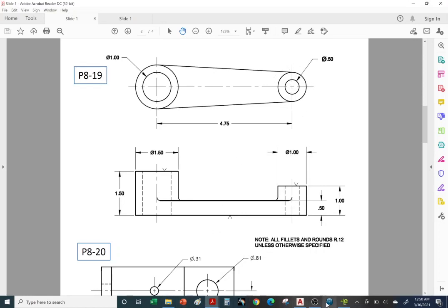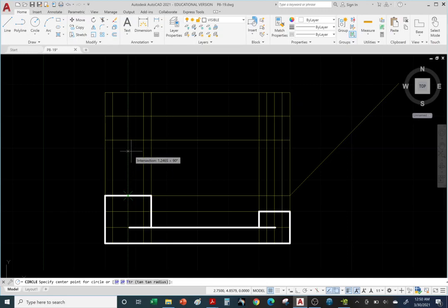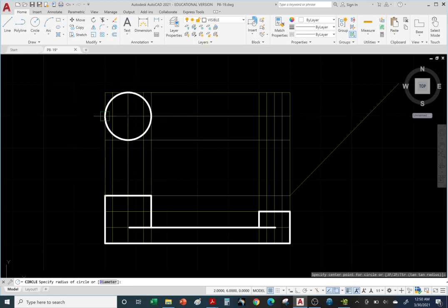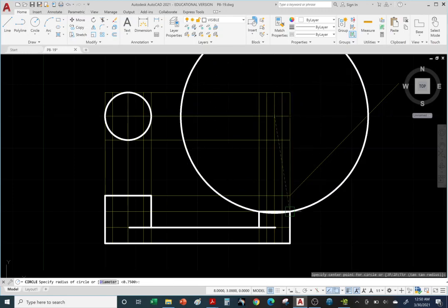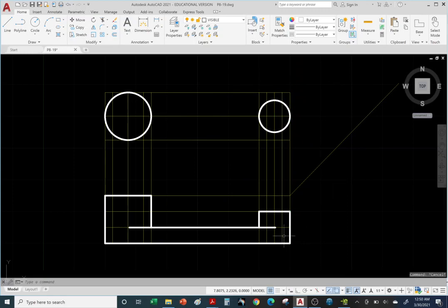Okay, so we're going to use our construction lines. Let's go to the visible layer, white visible object layer, draw our circles, and we're going to follow the center. Here's the center mark, click and go all the way out to the furthest quadrant, right? Follow that endpoint or vertex, click, go to the next circle, follow this center, there's our center mark, and click all the way out to represent the quadrant at that vertex. And there it is, and hit escape.